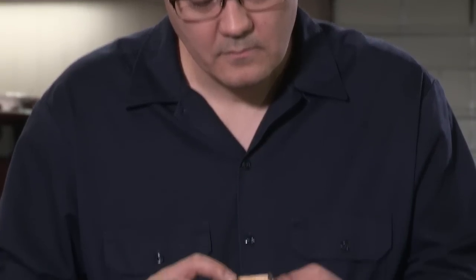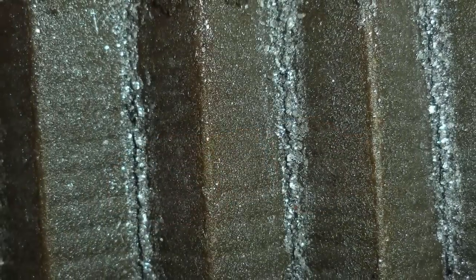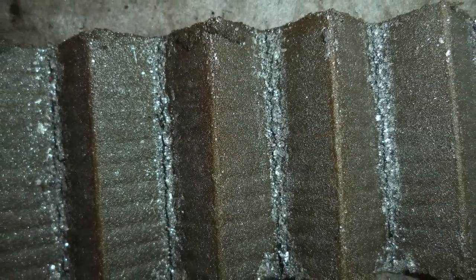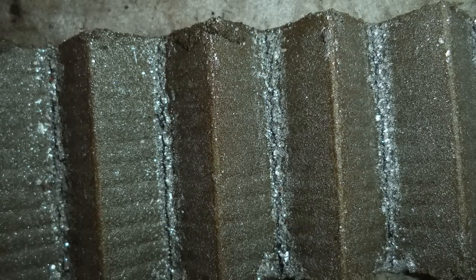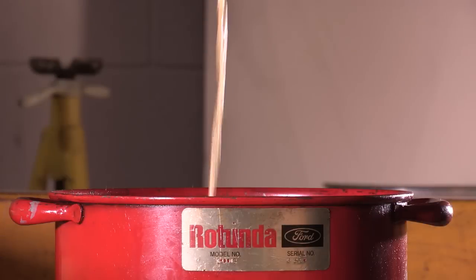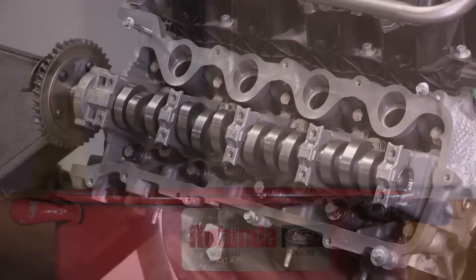If you suspect a bearing failure, inspect the engine oil and the oil filter. Excessive metal contamination found in the oil filter pleats may indicate internal engine issues. But take note, if an oil and filter change was completed just before this step, it can lead to misdiagnosis.